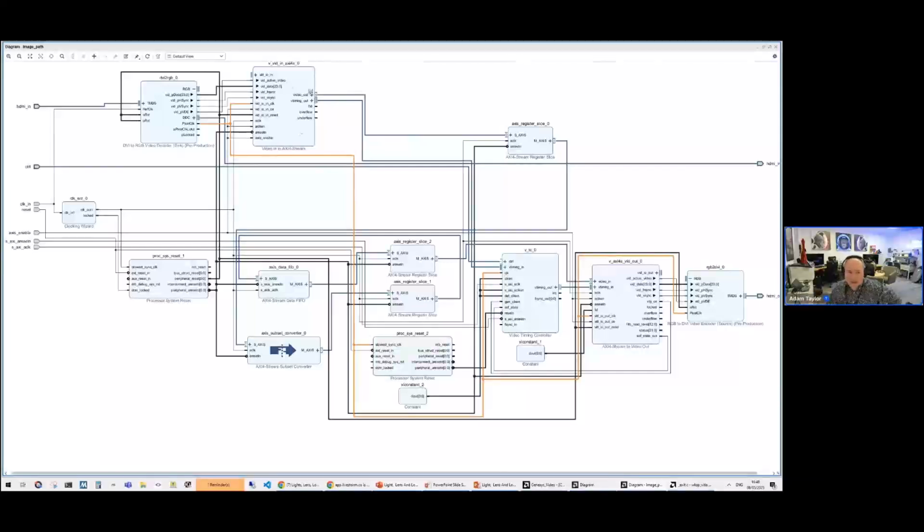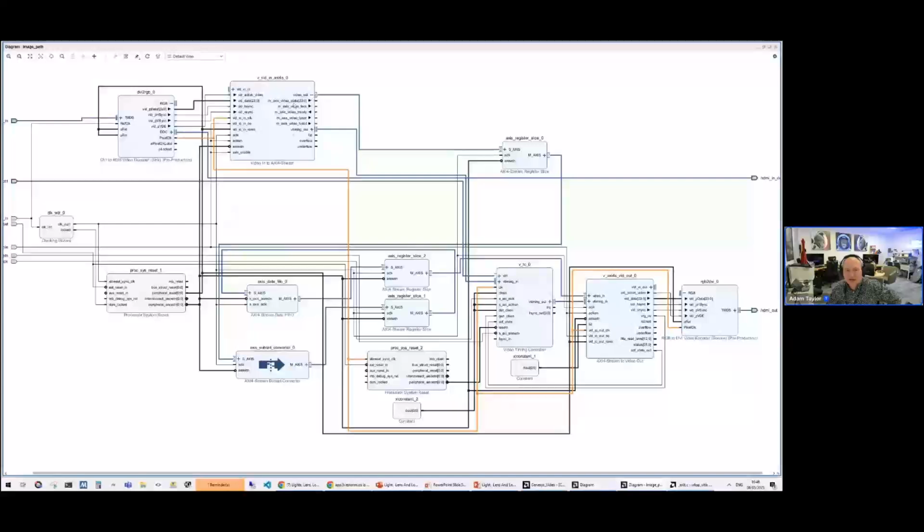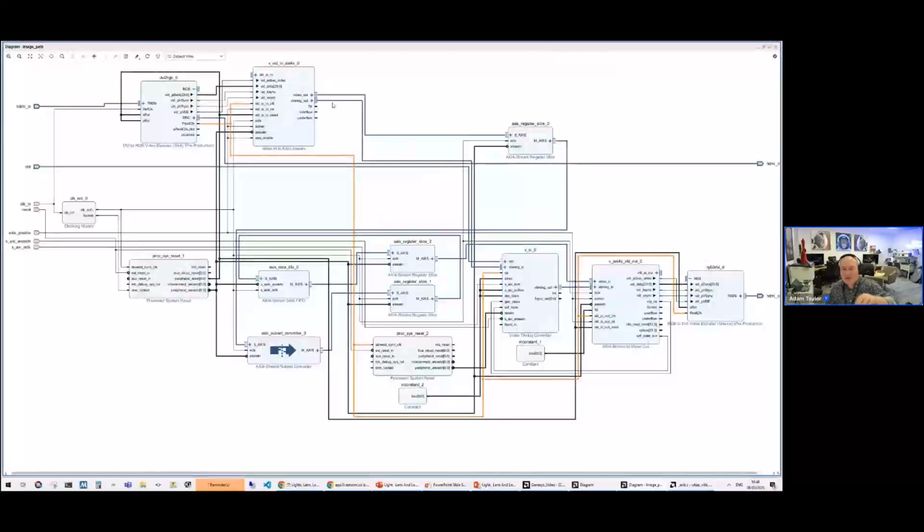If you take a look at the video out, you'll see we've got a TDATA, a 24-bit pixel because it's one pixel per clock. We've got the TLAST, the ready, the user, the valid, and it also gives us a video timing out signal. That video timing out reflects the timing provided in the horizontal and vertical syncs and any blanking information.